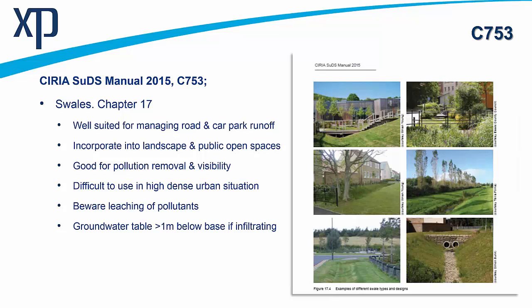And we've put in their visibility because it was mentioned in the SuDS manual that if there is polluted runoff, it is clearly visible within the swale itself. You can literally see it. So it's not buried under the ground and piped away and passed downstream somewhere.